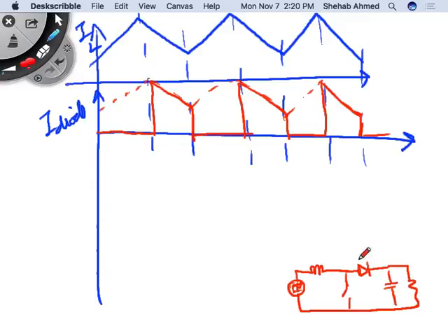This is current flowing through here. Part of this current will go into the capacitor, and part of it will go into the load, right? This is Kirchhoff's current law at this node. It has to be divided, right? So, assuming this is a very large capacitor, an infinitely large capacitor, what is the impedance to AC? Exactly. The impedance to AC will be 0. So anytime there is an AC component, this will look like a short circuit. The short circuit is definitely easier for AC components to flow through than the resistor.